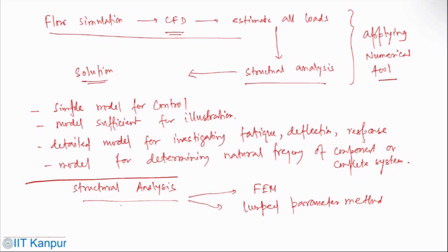For example, the drivetrain of a wind turbine in reality consists of a number of rotating components such as the rotor itself, shaft, gear, generator rotor. So to model a drivetrain, it is common to characterize it as a few lumped inertias and stiffnesses.